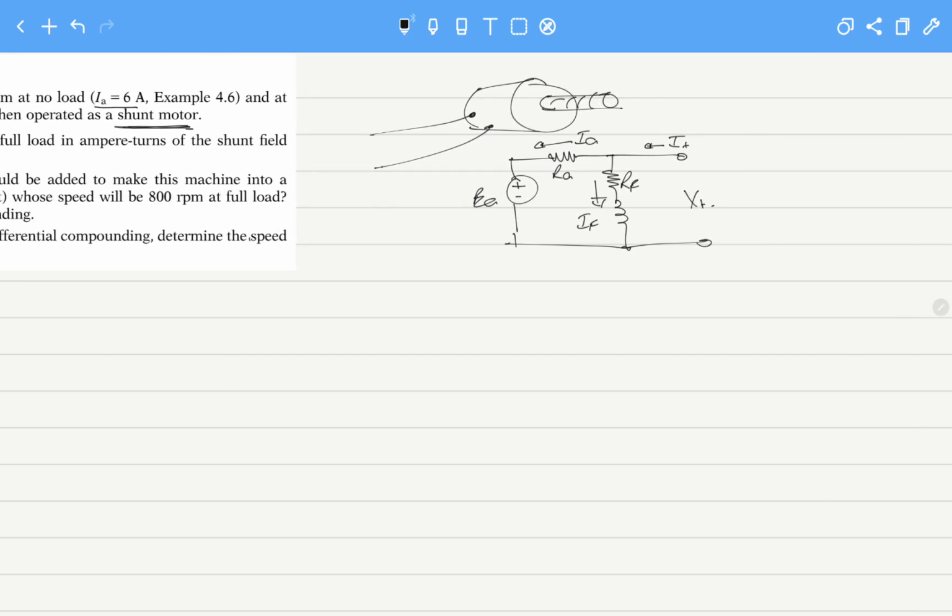So for the voltage control for these types of machines, there is a very typical example where we have speed here, and we have the torque-speed characteristics. This is a very important speed. For example, a motor has a base speed, and we call it omega base. Base speed is actually the rated speed of a motor, that is its nameplate rating, for example 1000 rpm. So what we can do is control the speed of the motor from 0 rpm to its base speed, and also beyond its base speed.